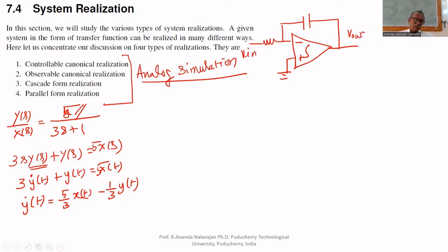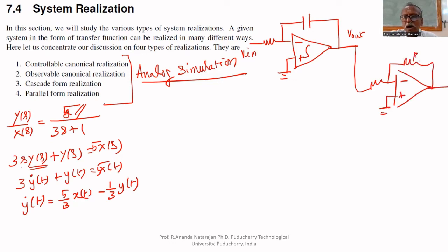That is the only difference. So by using an integrator, if you put a sign change here, how to put a sign change? Both are R, no gain, only R. If you put it like that, you will get the integral output without sign change.